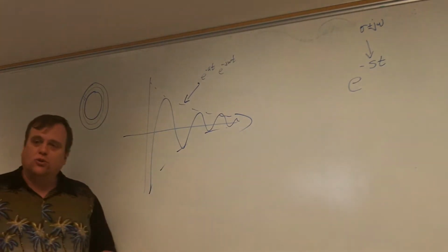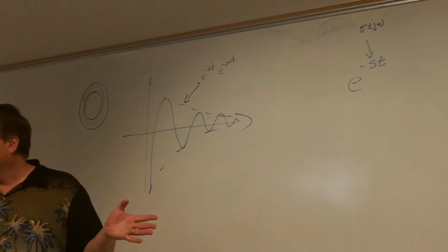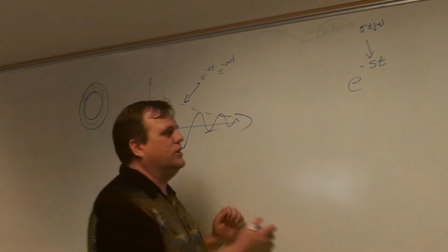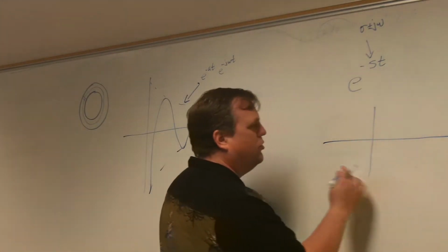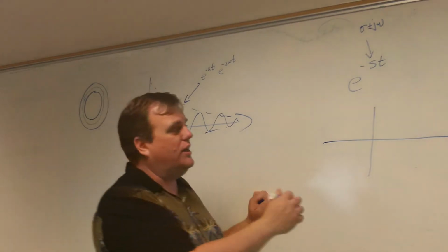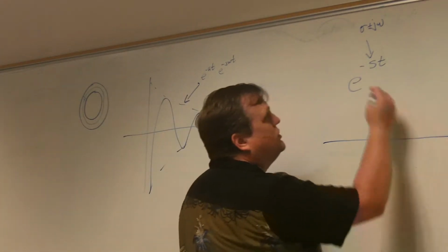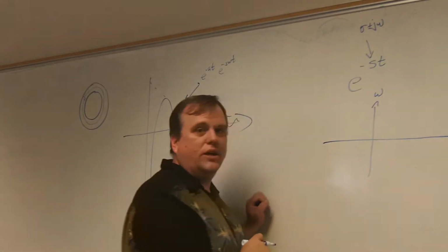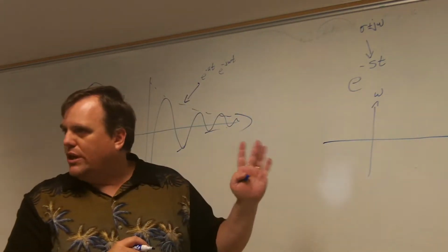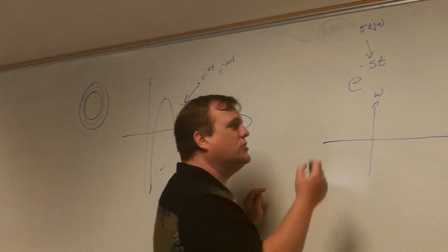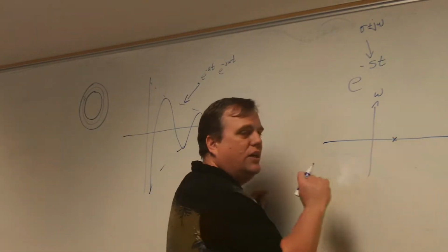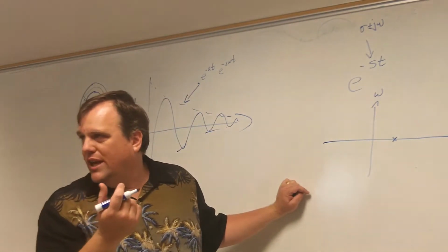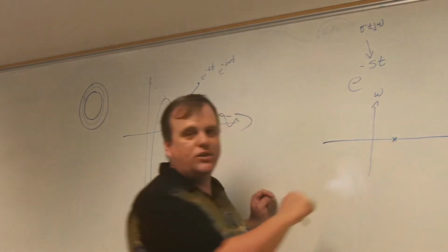Now, so that's one thing. And you'll see they'll talk about regions of convergence. The big thing that you will see within their regions of convergence, and I'll show this in a sec, but let me at least introduce it while I'm going through here. If I look at the complex plane, so the complex plane in our mind is now sigma, the real value, and then I've got my omega variable running up this way. And so if I'm looking at those as I'm going inside the complex plane, there's going to be certain points where there are infinities. Okay? We call these poles. And it turns out your region of convergence can never contain a pole.